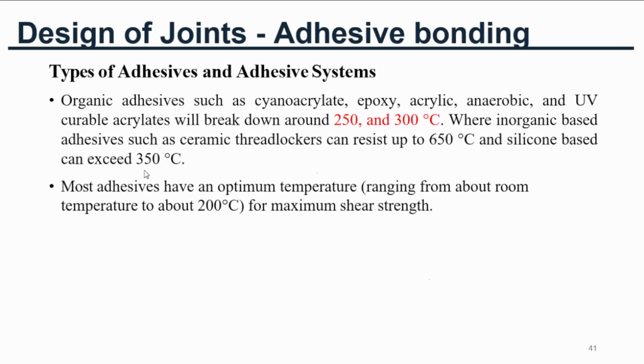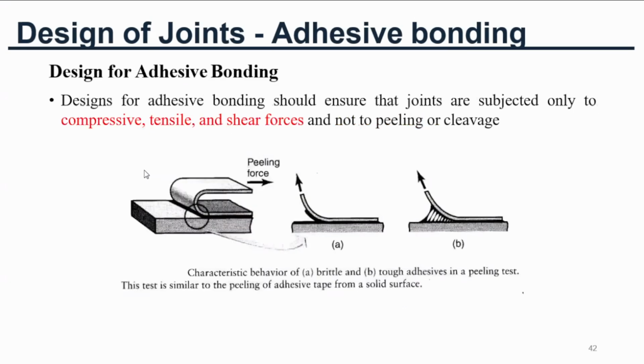So inorganic adhesives, ceramic based thread lockers, can withstand temperatures up to 650 Celsius. Silicone-based adhesives can resist temperatures exceeding 350 Celsius. Most adhesives exhibit maximum shear stress at their optimum operating temperature, typically ranging from room temperature up to about 200 Celsius.